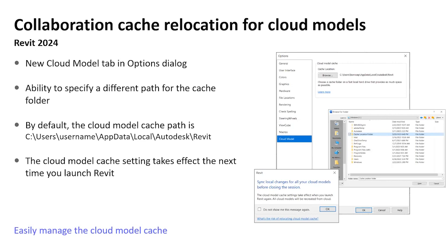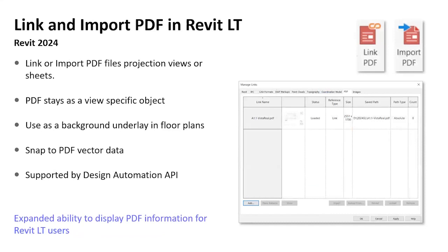That's your Revit local file. You can find it within the username app data folder, and now we can move it. We're not going to move it to the cloud, but we're going to move it somewhere where we can get easier access to it. I've always had just a shortcut to that location, but now you have access to the cloud model. Control where you want to save local copies when working on Revit Cloud in the Autodesk Construction Cloud.